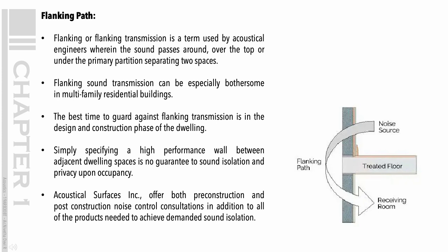Flanking sound transmission can be especially bothersome in multifamily residential buildings. The best time to guard against flanking transmission is in the design and construction phase of the dwelling. Simply specifying a high-performance wall between adjacent dwelling spaces is no guarantee of sound isolation and privacy upon occupancy.